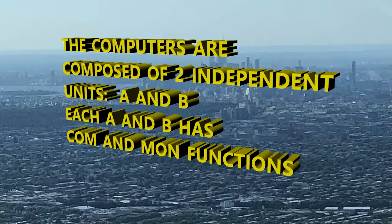Each of the units is going to be in charge of dedicated actuators, and the way it's segregated, what's doing what, is that one may be in charge of the left wing actuators. So it's broken up into left wing, right wing, and your tail. Left, right, and tail, as far as the grouping of actuators that are going to be affected by the primary flight control systems computers.